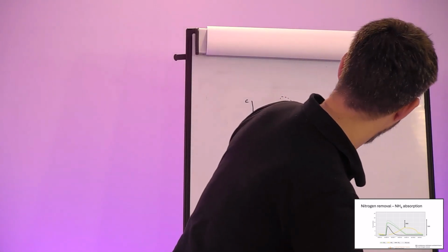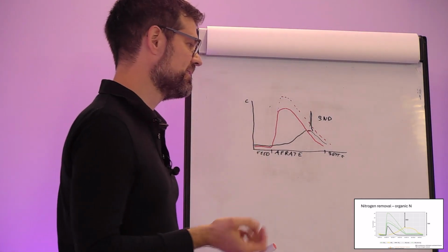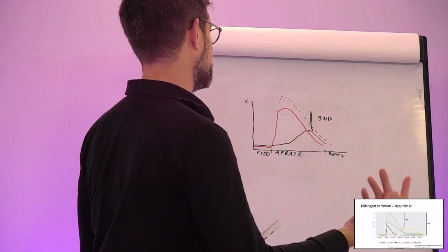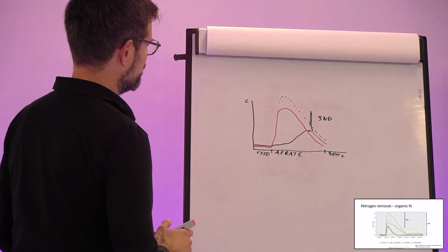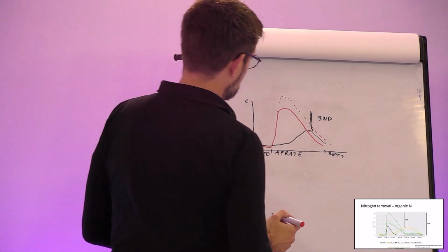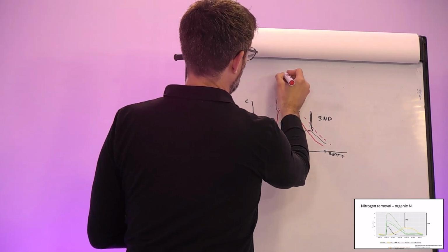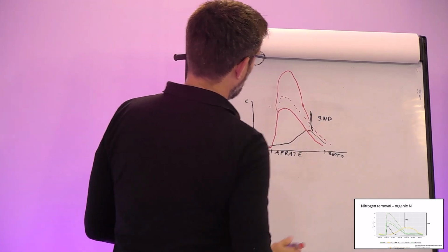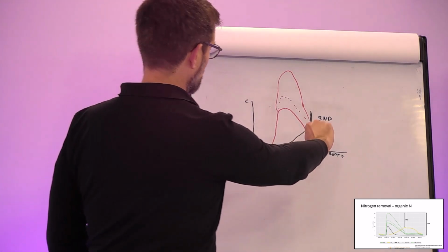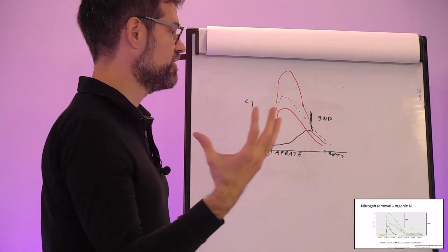On top of that, we also have organic nitrogen. You also don't see that in the sensors, but it is hydrolyzed during the main aeration and converted in the end to substrate and nitrogen gas, and that can be up to 50%. So this peak is even higher than what we see. And if we look at the simultaneous nitrification, denitrification, and also what is converted in the post-denitrification, that's what I call in the presentation total nitrogen removal.